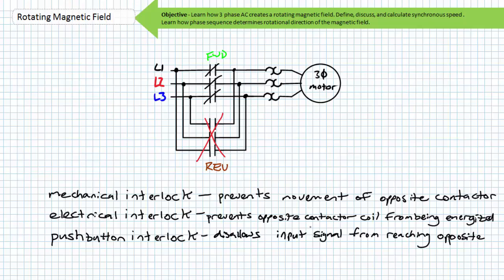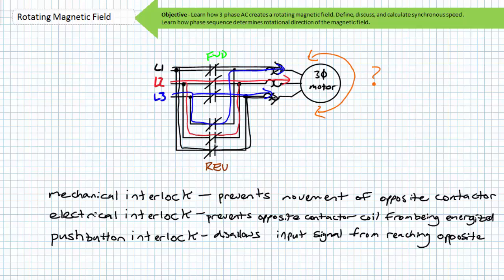We'll discuss reversing motor starters and various interlock methods in later lectures. For now, you should be reasonably savvy enough to understand that the purpose of these methods, separately or in combination, is to prevent simultaneous closure of both the forward and reverse contactors. Not only does it not make sense to simultaneously spin a motor clockwise and counterclockwise, it is extremely dangerous to do so.